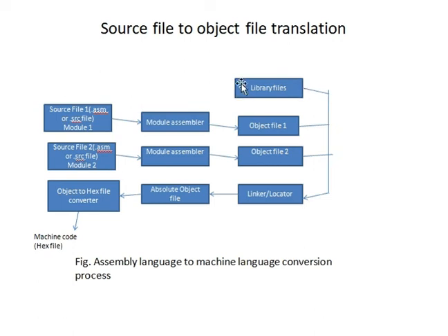Also, this library file includes the startup file, which runs the program as soon as you press reset; how the sequence of the program should run is addressed there. So the startup file will be executed, and that startup file is going to call the main program wherein you write this piece of code. And finally, once the program is completed, terminating the program is also addressed in it.